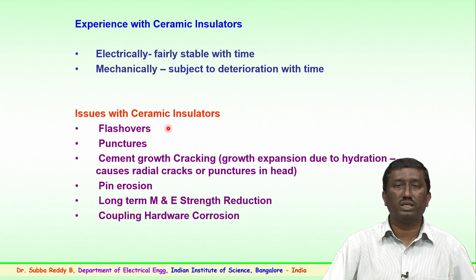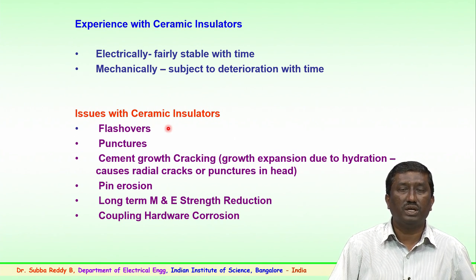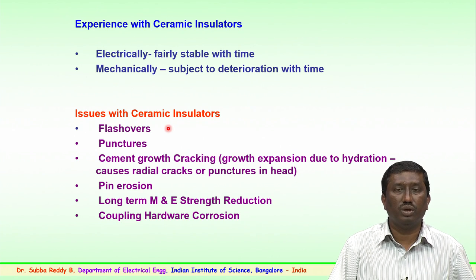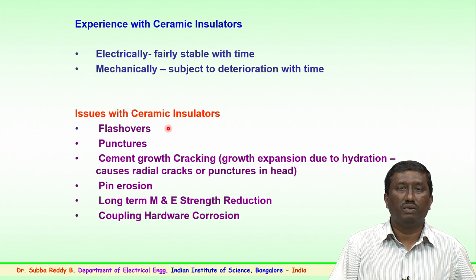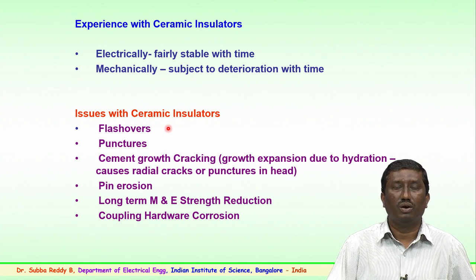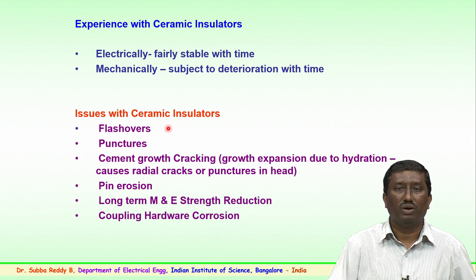The next issue is punctures. The puncture of insulators has also been noticed in the field, because of natural lightning, because of over voltages, or because of very sharp rise of surges. It has been noticed that punctures on the ceramic shell have happened and the insulation level has been reduced.